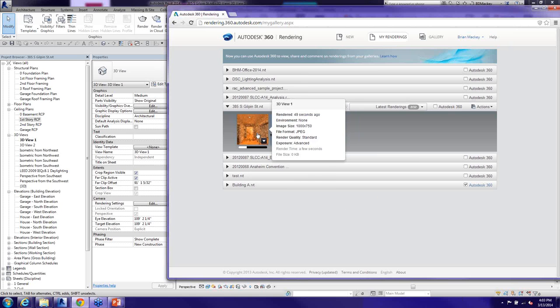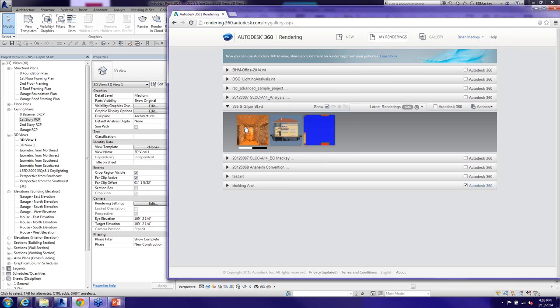So one thing I did want to point out is with the cloud rendering, you'll notice I did the same camera. It overwrites the camera you had if that view has the same name. I had this really good rendering, it was actually one I used cloud credits for, and I overwrote it with a draft rendering one day. So just make sure that if you've got a view and it's done, you possibly delete that view or immediately change the name of that view.